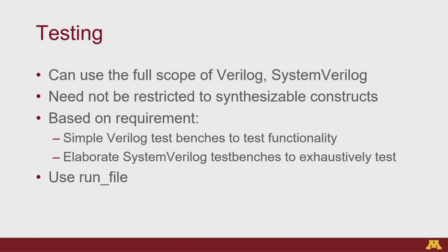Okay, so now that we actually have all of these things, right, we need to find a way to test our design. I won't go into too much detail, but I think the professor has uploaded a folder to your Canvas page, which is called FIR, if I'm not mistaken. That gives an example of a test bench and the design, the FIR design code which I've shown thus far, and kind of shows you the different scripts you need to run it. One of the scripts you have is this thing called a run file, that essentially tells you how you would run a simulation.